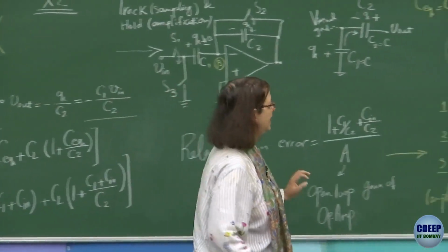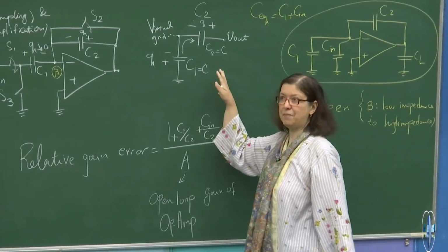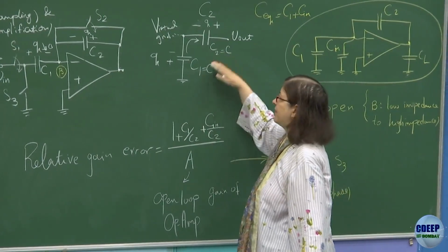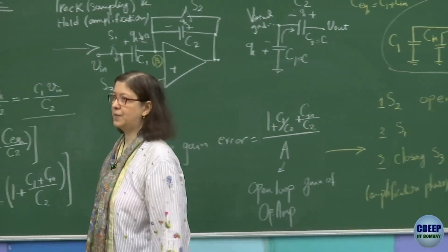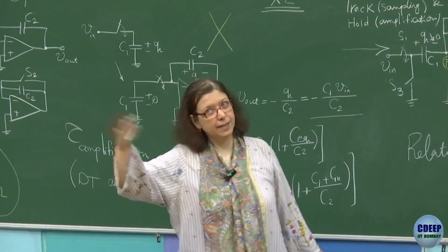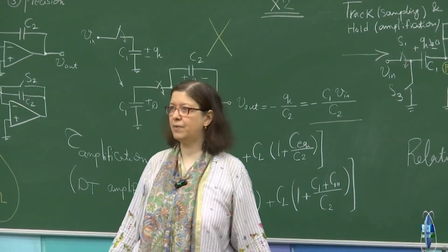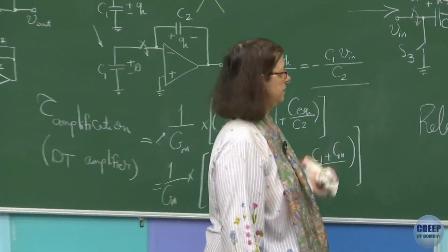Because then you are matching the two capacitors very well. C1 and C2 are exactly the same. So it is better to achieve a gain of exactly 2, because it is very important in MDAC gain. Otherwise, the effect of MDAC gain change will get transferred to the next stage and we will get error. Right? Okay. So that's fine.